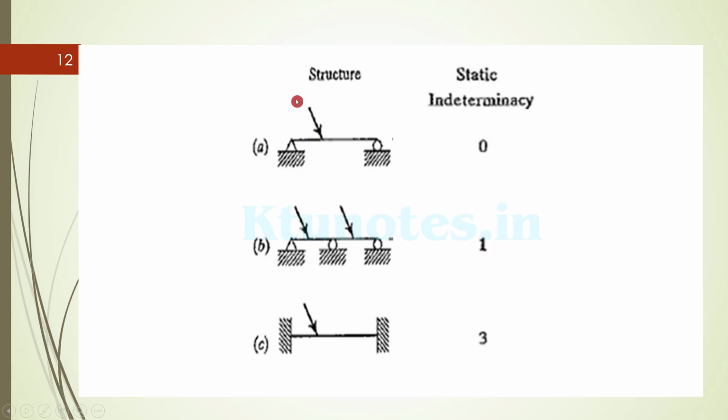Here due to the inclined force, this will create 2 reactions. For this hinge support, there will be a horizontal reaction and a vertical reaction. So there are actually 2 unknowns at the left support and 1 unknown vertical reaction at the right support. So 3 unknowns, 3 equilibrium equations, so it can be solved. So there is no static indeterminacy.